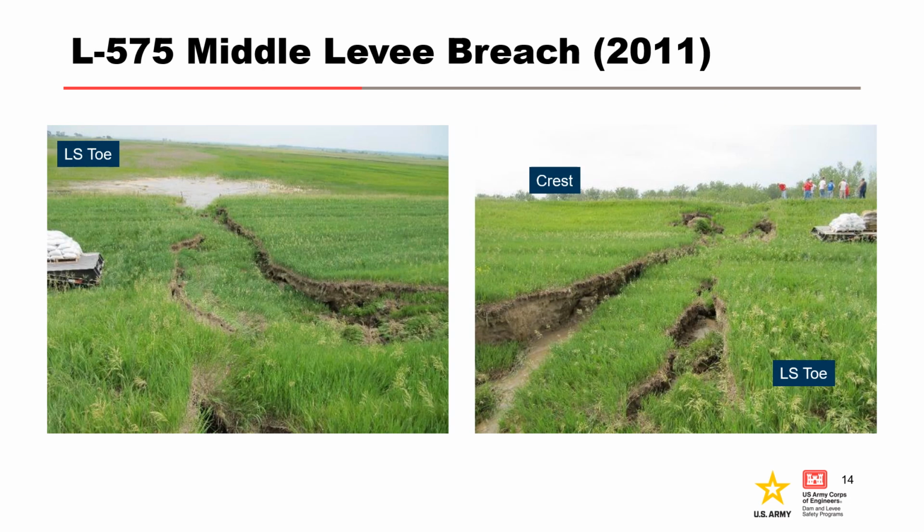With the Missouri River Levee Unit L575 breach, located west of Hamburg, Iowa, and just south of the Missouri-Iowa border, multiple pipes progressed towards the river, but it was the fourth one that ultimately led to breach. The first incident occurred on June 4, 2011. The levee sponsor noticed an approximately 10 to 15 foot wide slump of the levee crest. A contractor was called on site to repair. A second slump occurred on June 5th, about 100 feet south of the first slump. It did not develop into a full breach since the levee collapsed in on itself and shut off flow.